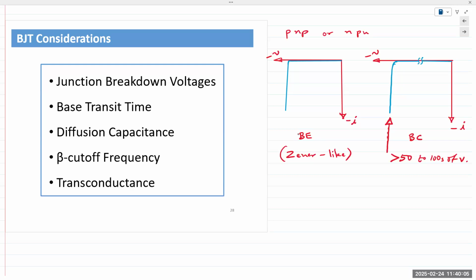You connect it to sweep and go, connect the base to the positive terminal, apply a negative voltage corresponding to the other unknown terminal. If you see a breakdown in the junction, meaning a current progressing in less than 10 volts, that terminal is the emitter. If it does not, then it's the collector. Make sense? Let me know if you have any questions. Yes.